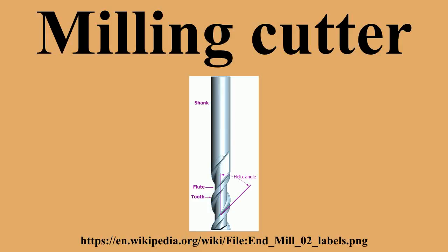Another type of shell fastening is simply a large diameter fine thread. The shell then screws onto the arbor just as old-style lathe chuck backplates screw onto the lathe spindle nose. This method is commonly used on the 2 inch or 3 inch boring heads used on knee mills. As with the threaded spindle nose lathe chucks, this style of mounting requires that the cutter only take cuts in one rotary direction. Usually this means only M03, never M04, or in pre-CNC terminology, only forward, never reverse. One could use a left-hand thread if one needed a mode of use involving the opposite directions.